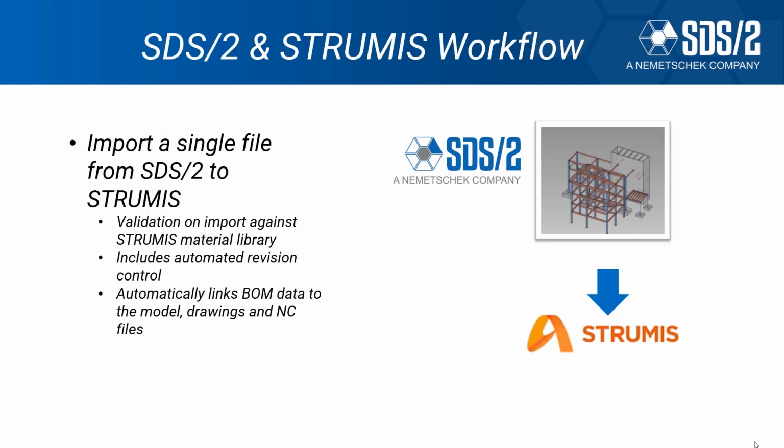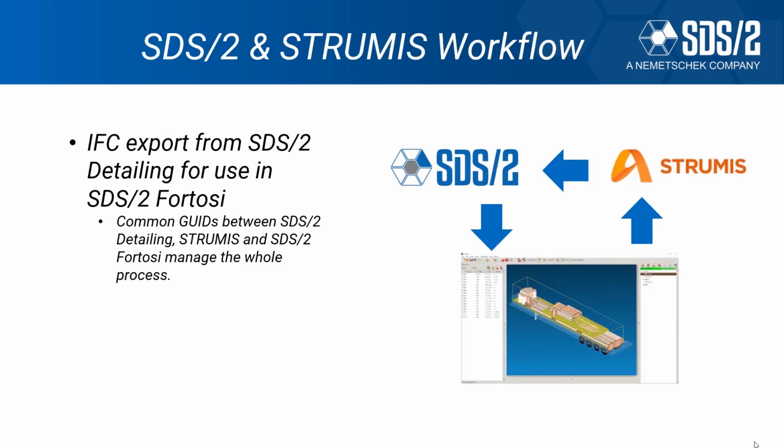Upon import, you're going to have the validation against the STRUMIS material library, and that will include automated revision control. It will also automatically link the bill of material data to the model, drawings, and NC files.